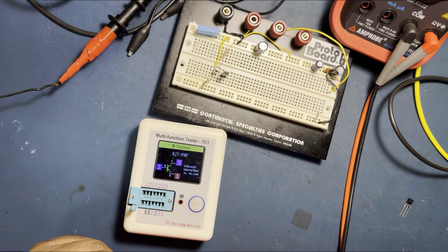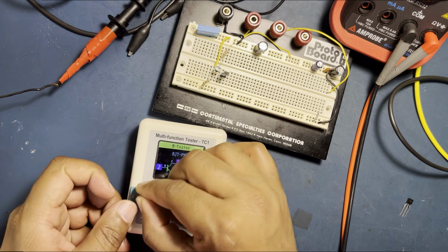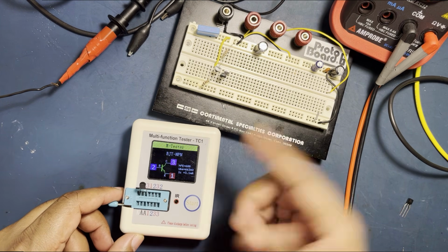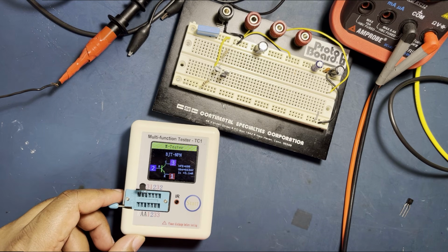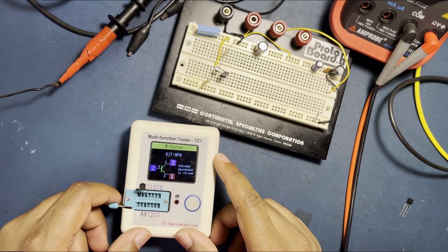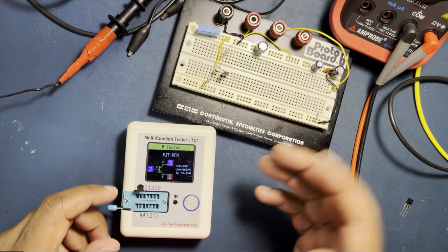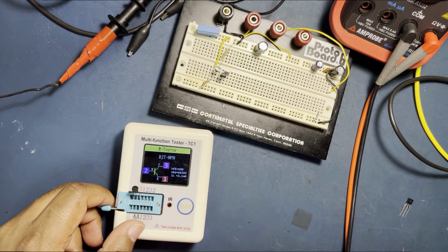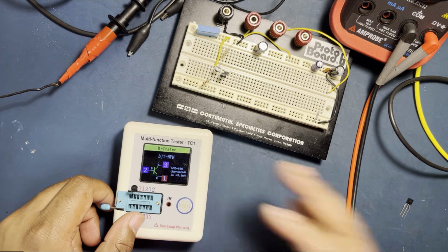Let's get one of the other NPN transistors and take a look at the beta for that guy. You can see this guy has a beta of 688, right? So 100 is reasonable to assume. We designed it for the worst case scenario, and most of our transistors here have a better beta, so they will act much better than what we designed them for, right?